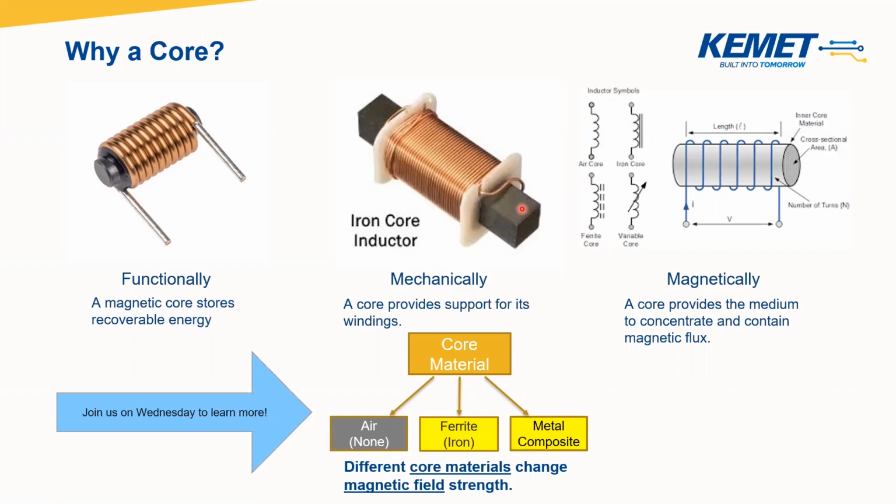Yep, and just to add on that, a few of the main parameters that you would need to consider, number one is going to be the inductance, and that's pretty obvious why. You're also going to need to look into the chip size or the dimensions of the part to make sure it's going to fit into whatever your application is. Another important thing is the temperature range. A lot of inductors are rated to roughly around 105 degrees C. Some of them, such as our MPX inductor, could get up to 155 degrees C. It's very important to know where that's at, because that temperature range is going to have influences on other parts of the device, such as the current, and that brings me to the next part.